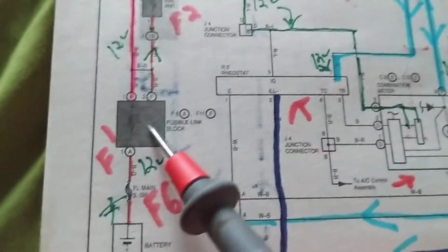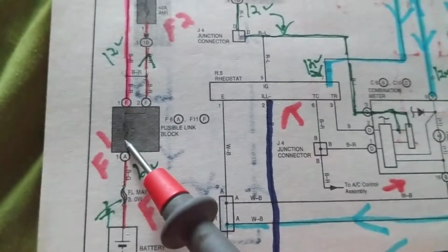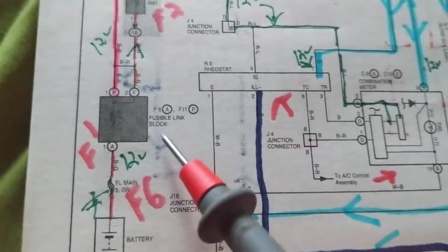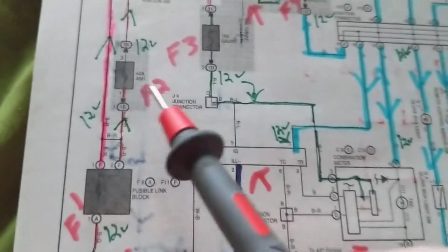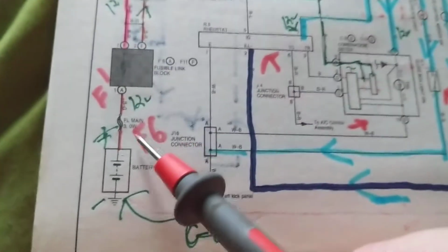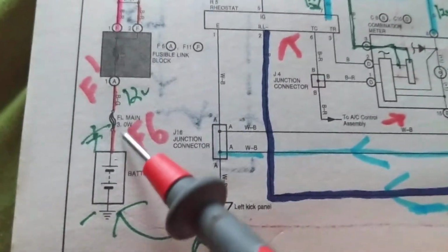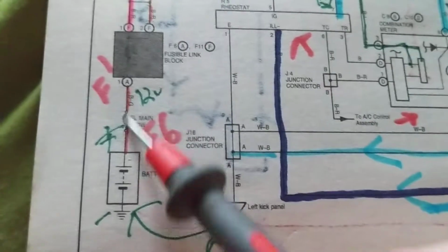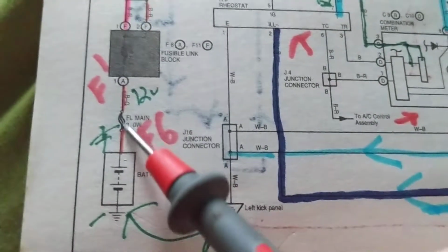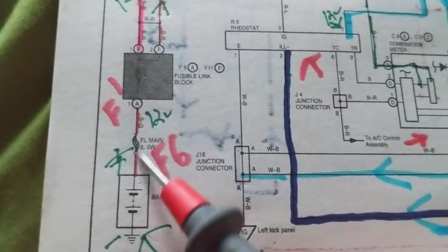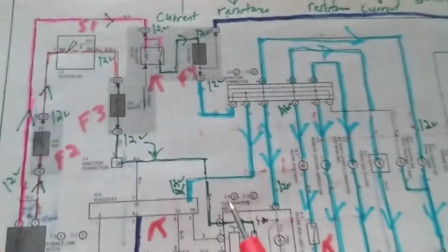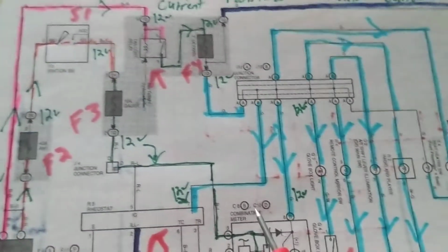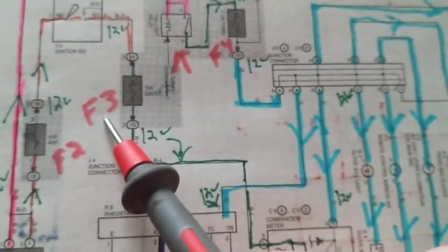This one right here. Again, how can we tell? This is thicker, wavier. Where's it located? In the fusible link block. They even tell you this is a fusible link. Sometimes they will not, but you have to know the symbols. Again, fusible link over here, the main one. See? Now you can see the waviness of it. Look at the difference between that and the regular fuse. So we have 3. If they ask you where you have fuses and the ratings, we have a fuse right here, F3.